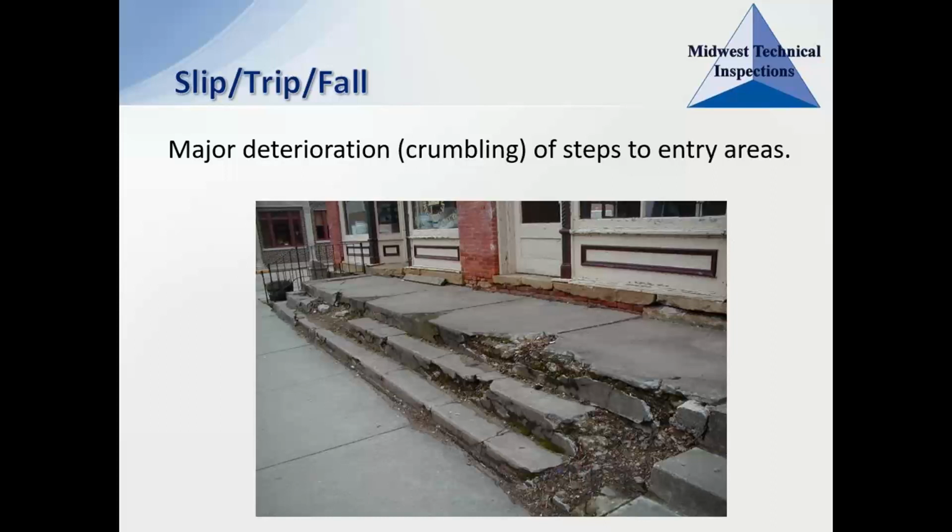but based on the condition of the stairs, one of the first things I would do is go over and give that handrail a good shake, see if it doesn't just come off in my hand there. I want to make sure that it's something that's going to be able to hold up a person. If they start to stumble or fall, they can grab it and hold themselves up with it. So assuming that it's in good condition, that it's solid and able to hold them, the next thing that I note is that it is all the way down at the far end. What happens if somebody tries to walk up the stairs over here? They're not going to be able to reach that handrail if they start to stumble and fall.